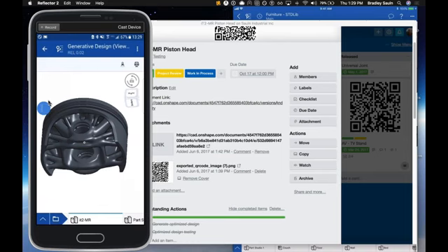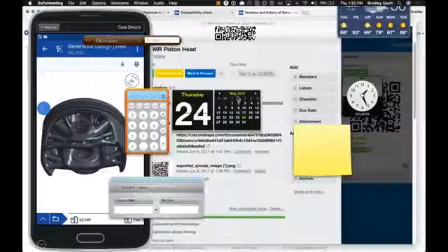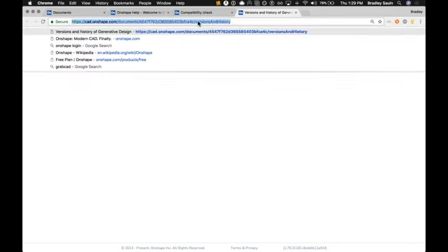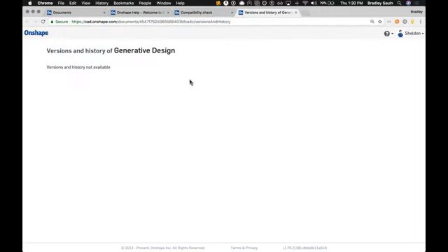Again, a pretty cool workflow to see, connecting your project management tool, something like Trello, with your Onshape engineering system. And I didn't need to use any API connection. This is just through using Onshape's URLs, links, copying and pasting them across different sections. And as you saw, the permission settings are maintained through that. I don't have to create a link permission set through our sharing system. I can just copy and paste the link from there, and anyone who's already been shared into that project will have access to it. Those that don't get to see that information.